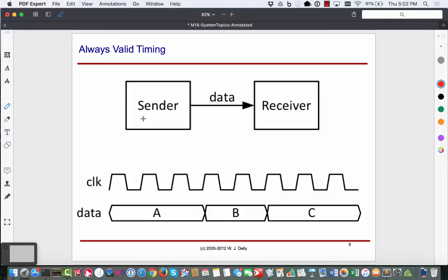So usually, when you look at these interconnects, which connect to devices and are serial in nature, they'll typically have a clock, and they will have a serial data line going one way, a serial data line going another way. So if you look at the USB specifications, there's a clock signal, there is serial data going one way, serial data going another way.